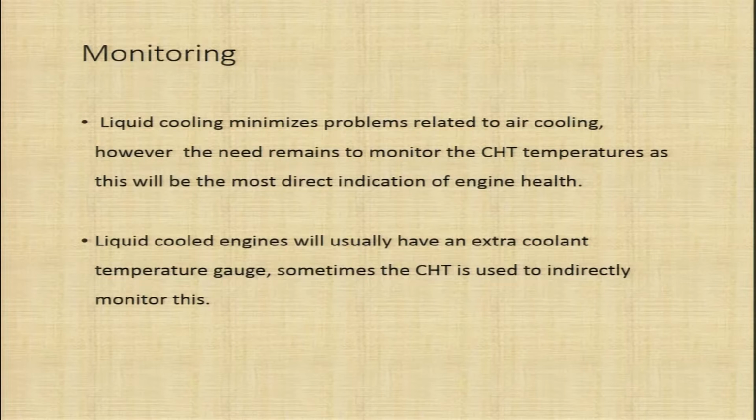Liquid cooled engines will usually have an extra coolant temperature gauge. Sometimes the CHT is used to indirectly monitor this. So, in case of liquid cooling, we will also have an additional gauge like the coolant temperature gauge or the water temperature gauge, which will give us the temperature of the coolant in addition to the cylinder head temperature gauge being used in all other engines.